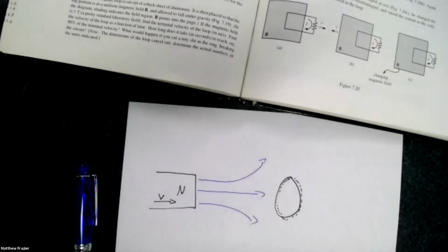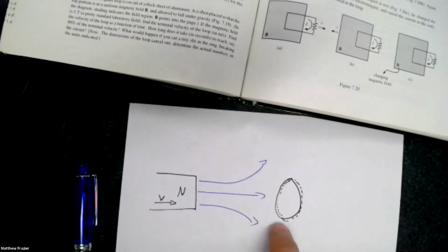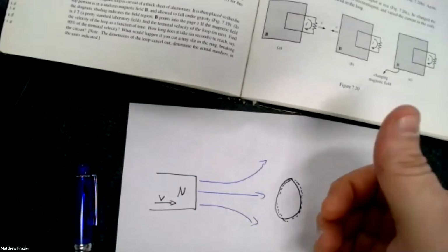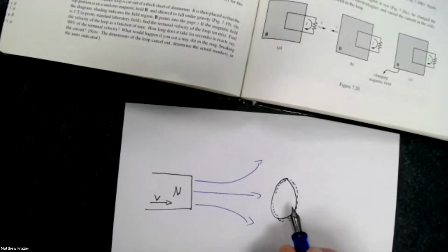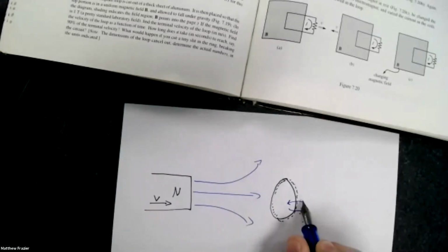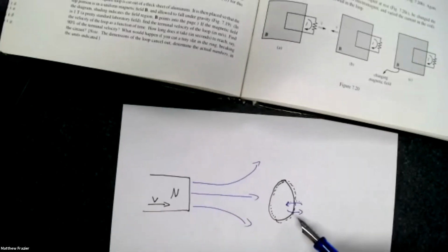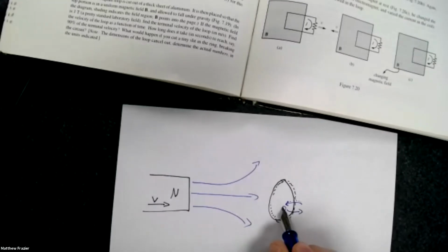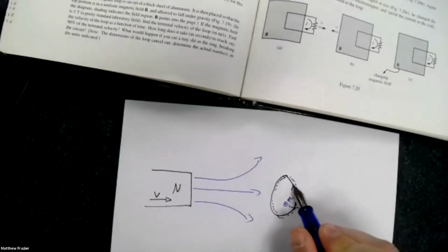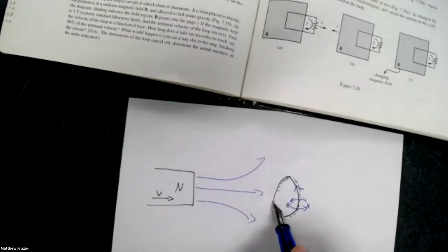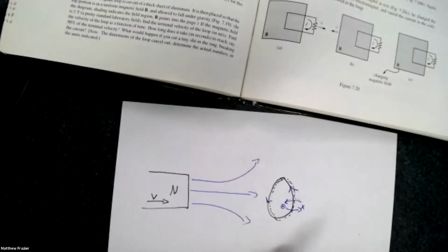So let's say the current flowed, and I'm increasing the flux. Applying Lenz's law with the right-hand rule, on this wire we want a magnetic field going this way. So behind, we want something that's coming out of the page here and into the page there. To do that, the current would have to flow upwards, and then it would flow downwards here. So that's applying Lenz's law.